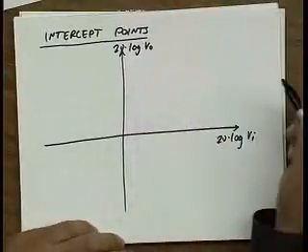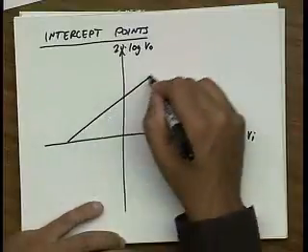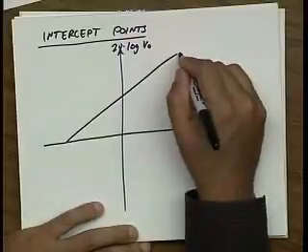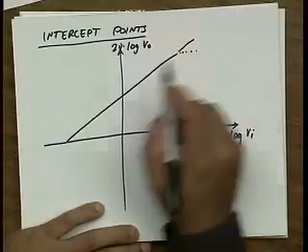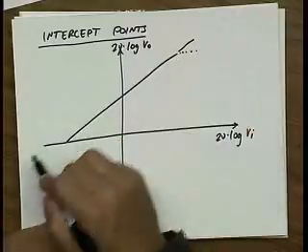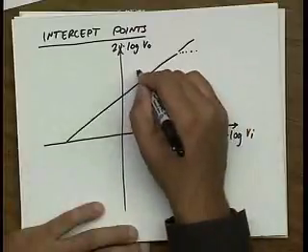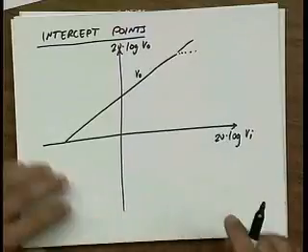Now, if I plot on this log-log scale the input-output relationship, I will get a curve, right? And because eventually there's gain compression, I know that if the input is sufficiently large, it'll start deviating from a straight line. But for now, let's focus on this straight line. So this is the output, or the fundamental, appearing at my amplifier.